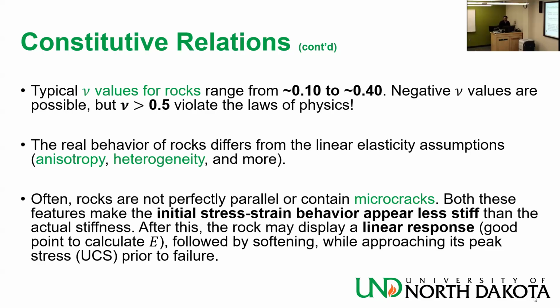If you are measuring the Young's modulus, make sure you measure it at a point where the material has already compressed enough that all the micro cracks have closed down.